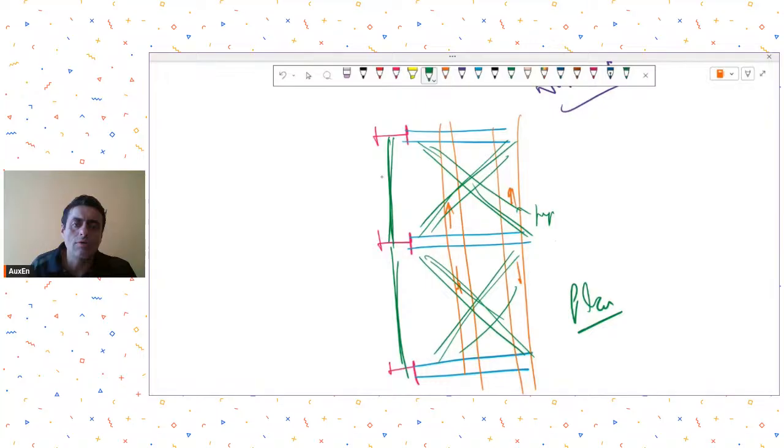Also, you can think of connecting these columns either through elevation bracings or some tie beam arrangement. So this will help to make your system better against those longitudinal forces. Clear? All right. So this is what you can do. Then let's move on to the next query.